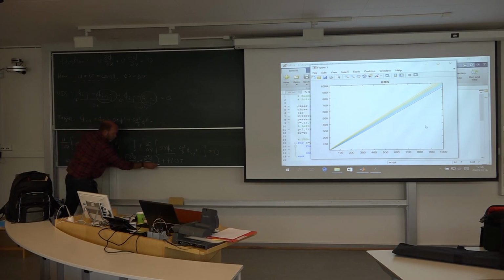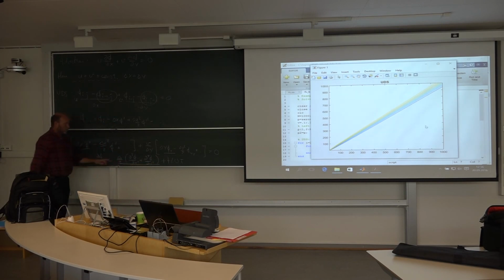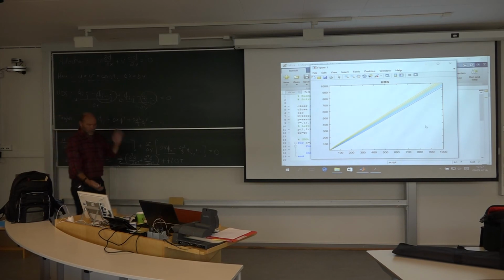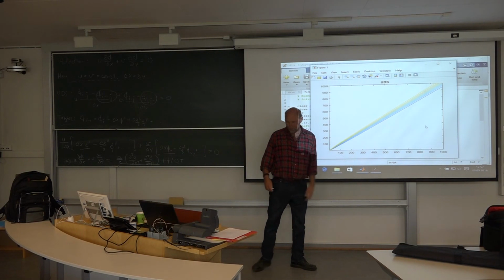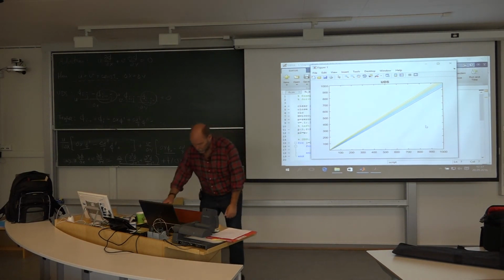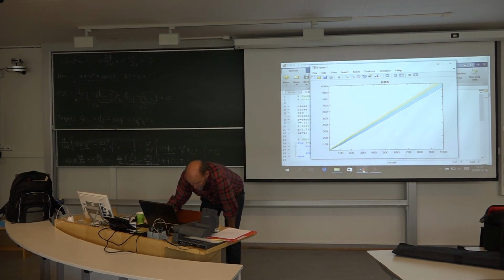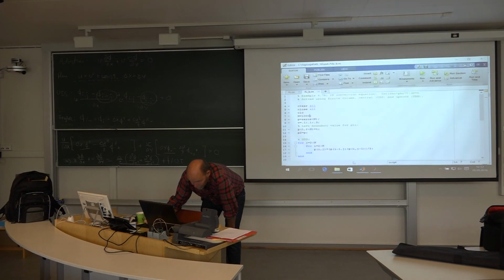You get a double derivative here with a positive term in front. You get diffusion, you get viscosity where you don't want it, and you see the effect. It smears out these gradients, and the fewer cells, the worse. Let's try with 20.